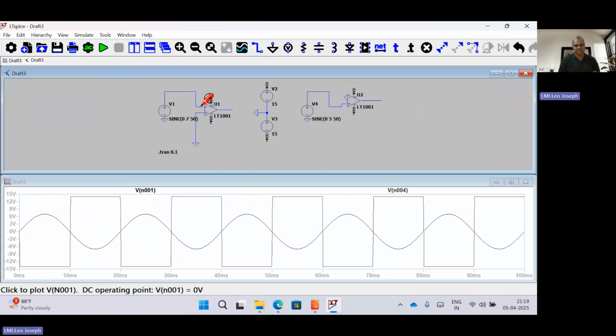Here, instead of seeing it as negative voltage, you see it as a positive voltage. When the positive point is coming here, this becomes -5. This is positive voltage, so positive voltage is applied here, which means this becomes minus and this becomes 0. So this will become negative, -V saturation will come.